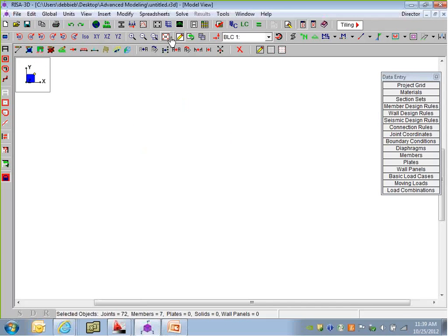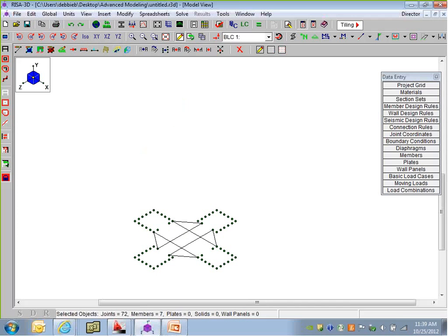And one thing to be very careful of is that you don't just draw all of those and model merge quickly and not know that it had consequences. So model merging is a good thing most times, but sometimes it can get you into some trouble that you didn't realize, especially with crossing elements.